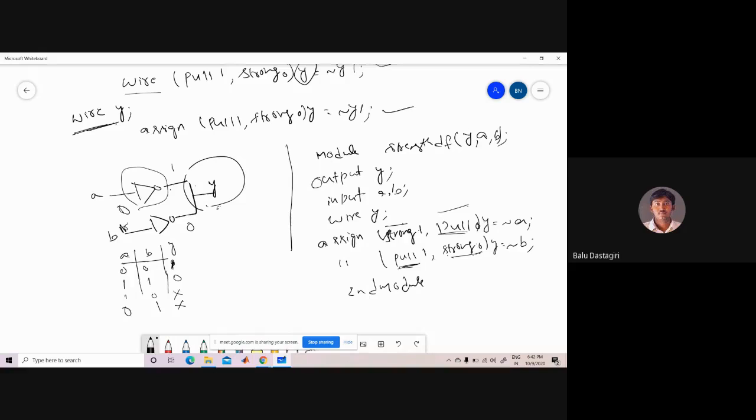Therefore here we have to go for the declaration of the things which I have told you. So we have to go for the declaration of wire, wand, or var. You can declare the output again in terms of wand y.